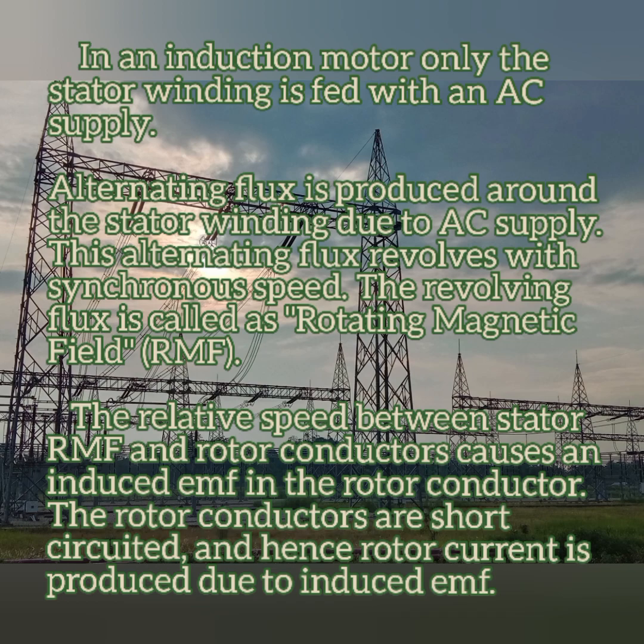In an induction motor, only the stator winding is fed with an AC supply, which means a single phase or three phase AC supply is used for the stator winding, and an alternating flux is produced around the stator winding due to the AC supply. Then this alternating flux revolves in the motor at synchronous speed. So the revolving flux is the rotating magnetic flux, which means the rotating magnetic field.